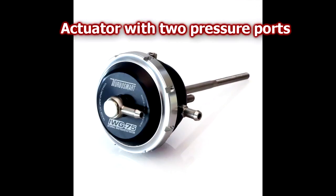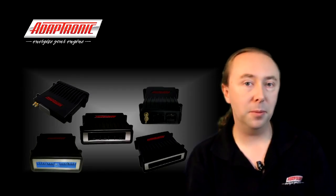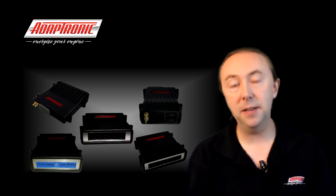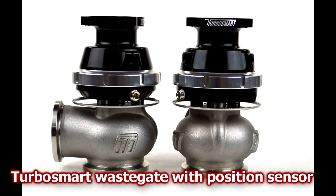Now on some actuators both sides of the diaphragm are sealed and they have ports going to them, so you can control the pressure to either side individually. And on some of them there's only a port on one side, which is the side that you need to put pressure into to make it open, and the other side is just open to the atmosphere. And these are normally called single port or dual port actuators. There are other differences with actuators as well. Some wastegates are liquid cooled, and some of the Turbosmart ones actually have a rod that sticks out, and you can get a position sensor to actually measure the position of the gate to help with diagnosis.